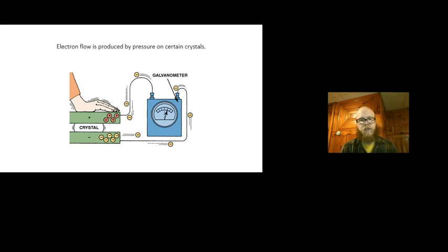Piezoelectric device, so you could think of a knock sensor as just about the only thing on a car that is this style. The pressures of detonation or pre-ignition will cause that sensor, which is tuned to a certain frequency, to respond. That frequency happens in a specific motor, through the metal, whether it's aluminum or cast steel. When you hit the right frequency from one of those events, voltage is created.